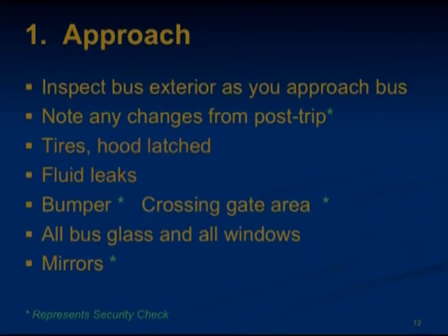Check the bumper and crossing gate area for hidden objects as part of the security awareness sweep. They should be secure with no hanging objects or loose wires. And all bus windows and glass should be clean and not cracked, free of illegal stickers. Windshield wipers should have good rubber and touch the glass. Mirrors should be mounted securely with no broken or cracked glass. They should be clean, properly aimed, and tightly adjusted.